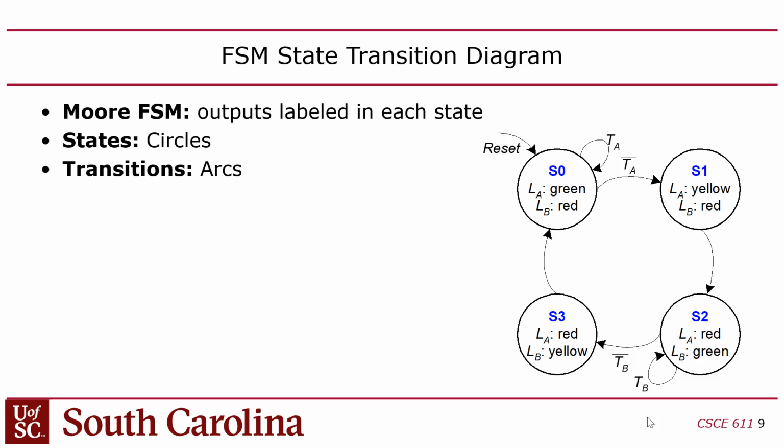So what's happening here is that if we're in state S0 and I have traffic on academic, and the green light is on academic, I want to stay in that state, right? So when the clock edge, next cycle comes, we're going to stay in there. And so there's that loopback connection, right? And then if there is no traffic on academic and the green light is on academic, then we should begin transitioning over to putting the green light on bravado. Of course, we have to go through the yellow light state first, okay?